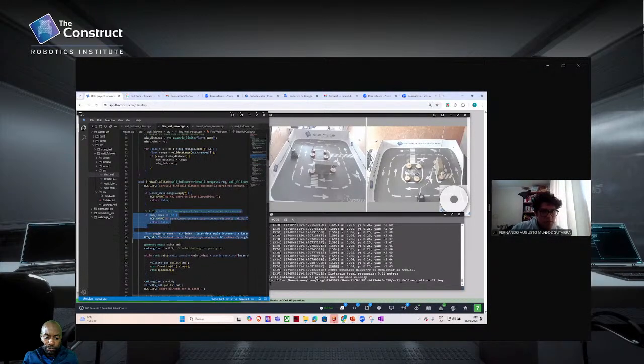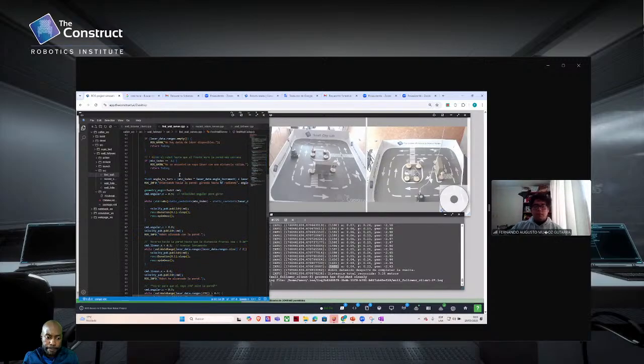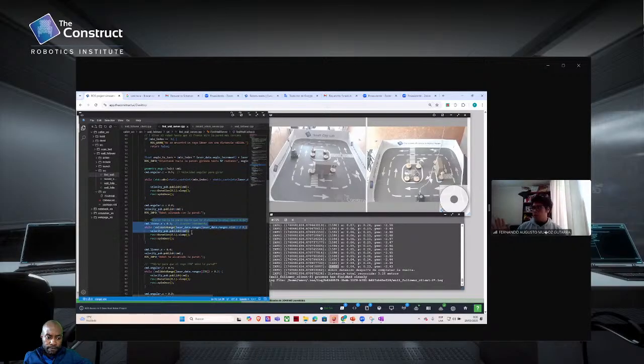In this case, first the sequence is not too difficult. I think that part is the most important to start. First, we see the robot starting in any position to lift the logs. In this part, the robot rotates toward the closest wall. The robot calculates the angle of the closest laser ray and rotates until the ray is centered in its field of view. Then, when you localize it, we move forward toward the wall.